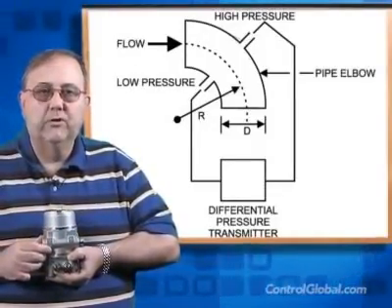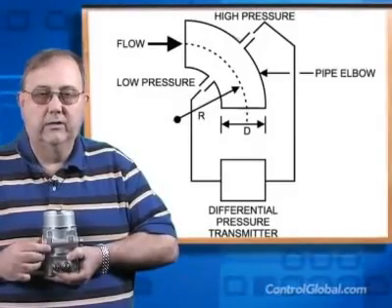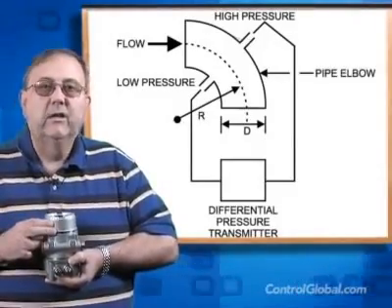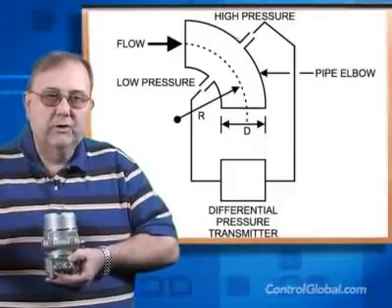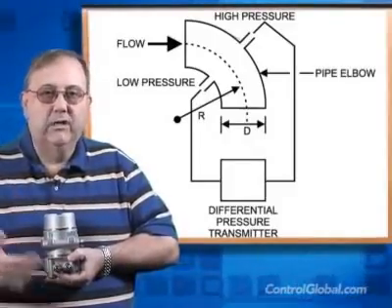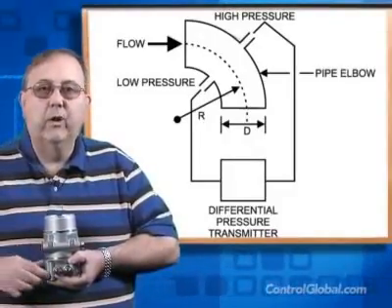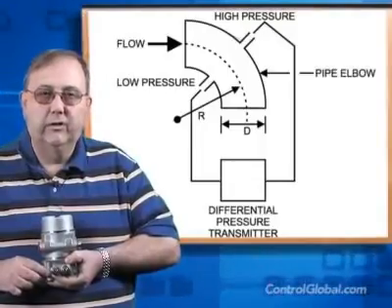Differential pressure transmitters have been designed using many technologies, including capacitance, differential transformer, force balance, piezoelectric, potentiometer, strain gauge, and vibrating wire, and many of these techniques are still in use.